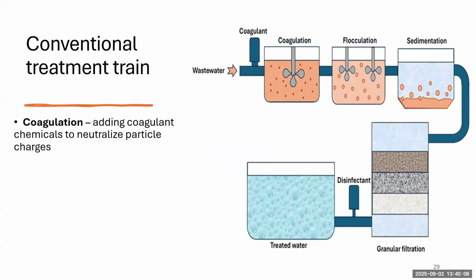So we're going to move into the water treatment process, and we're going to be looking at 4 removal processes basically. First of all, we begin with coagulation. Basically what that is, we're adding a coagulant chemical, which is going to neutralize the charge of particles. Particles tend to exist in raw surface water as negatively charged particles. We're going to talk about that more, but the coagulant addition destabilizes those charges so they can begin to clump together to make larger particles.